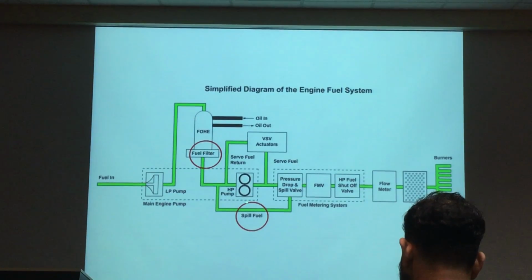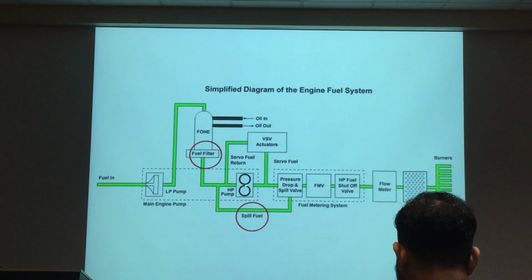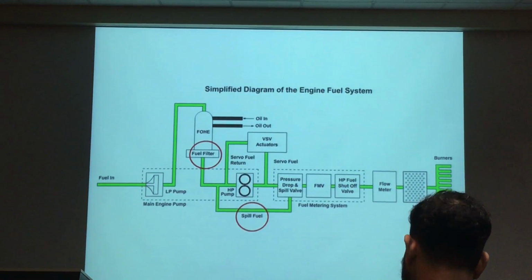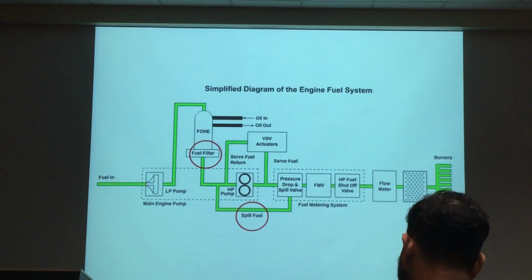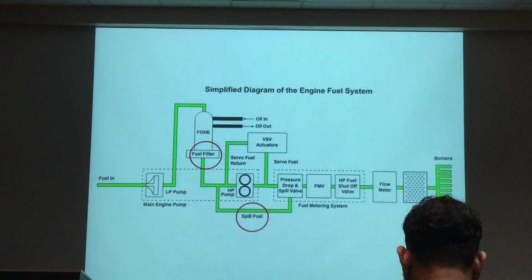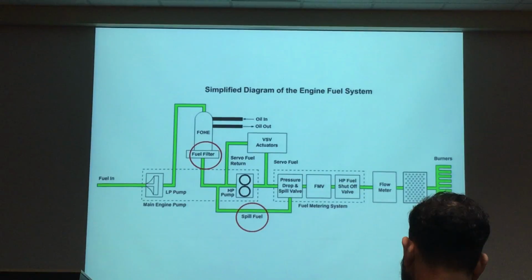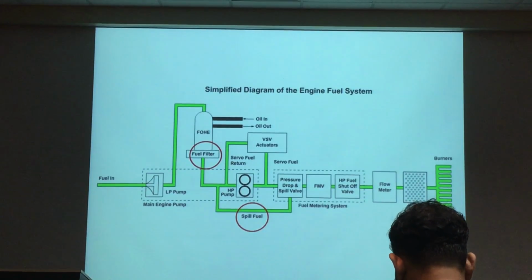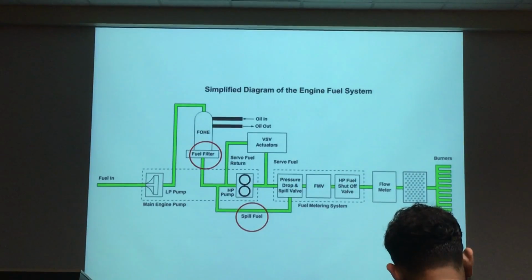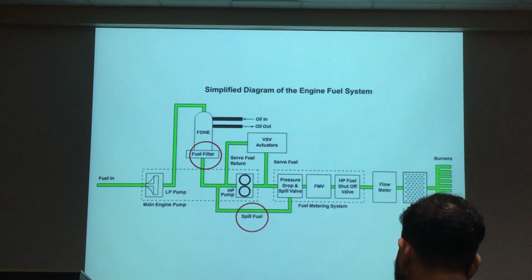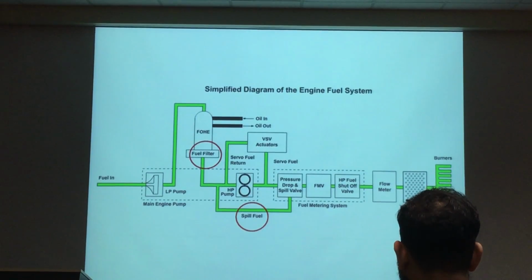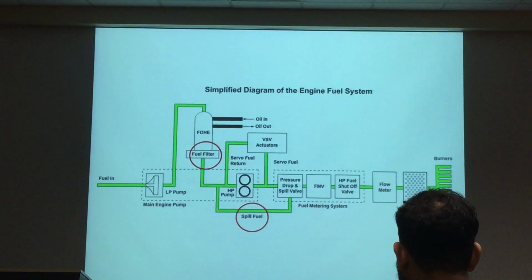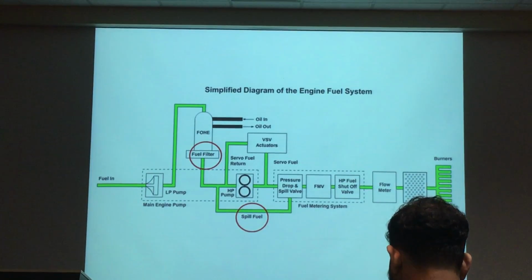Okay, after your pump, the pressure here is used as your hydraulic. It's your fuel hydraulic to actuate your engine actuators. Your engine needs muscle to move the valves, to move all the vanes, to move all the big valves. The muscle comes from the fuel hydraulic. Not the aircraft hydraulic system, please. Don't get confused. You're using fuel hydraulic. Although the engine drives a hydraulic pump, and this pump drives the aircraft hydraulic system, the thing that moves the engine components is done here, under fuel hydraulic. Understand? Don't confuse it with the aircraft system side.